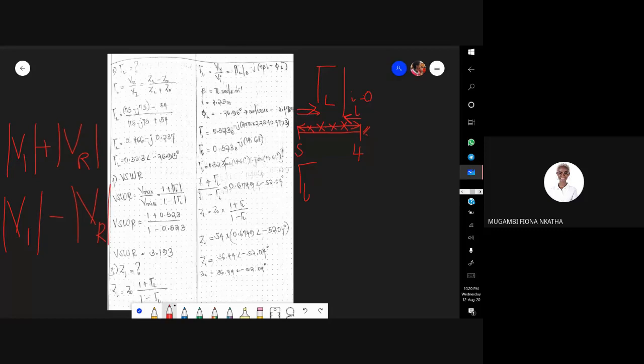When you substitute this, and also substitute those formulas for gamma, where gamma L is equal to VR over V incident, you'll be able to find this formula here. So when you do that, you get the voltage standing wave ratio as that.